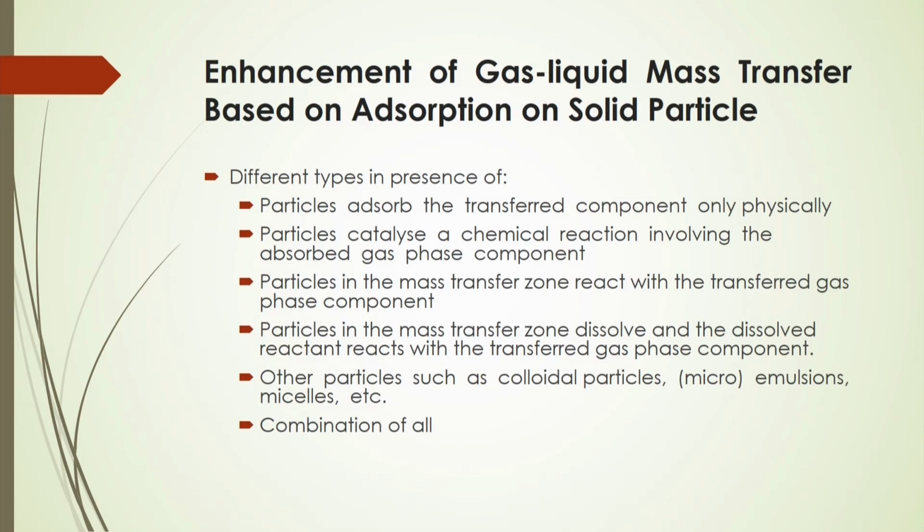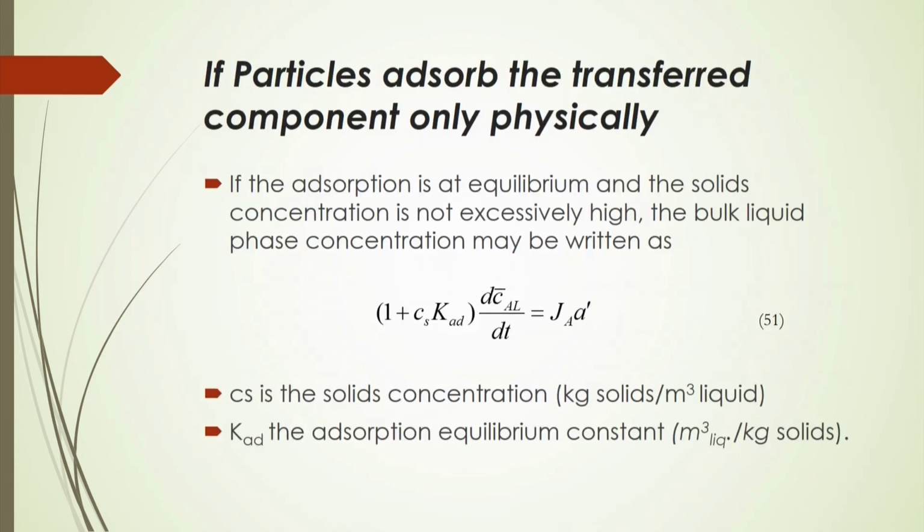And you will see that in most of the cases there will be adsorption of the components on the surface of the solid particles, and the reaction will be on the surface. Other particles such as colloidal particles, emulsions, micelles etc. also may change the mass transfer rate inside the fluidized bed, and a combination of all these possibilities may enhance the mass transfer inside the fluidized bed.